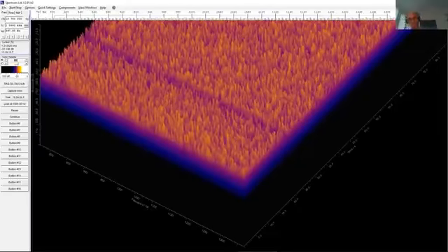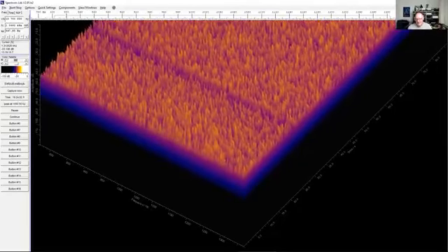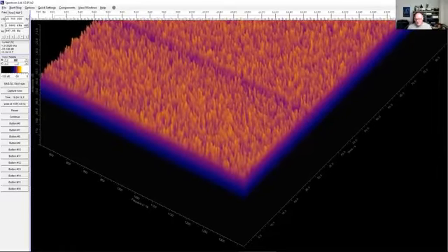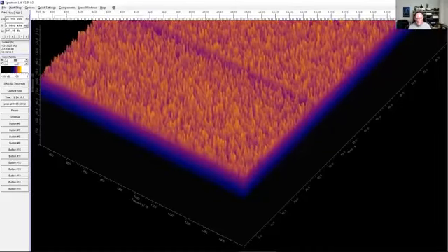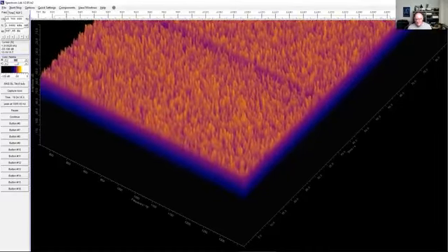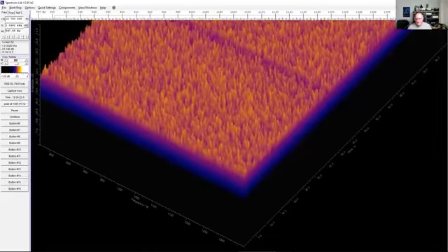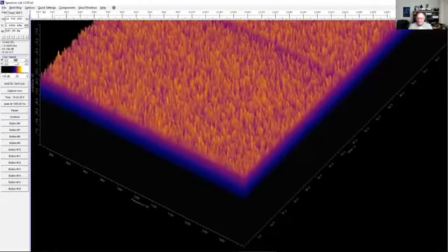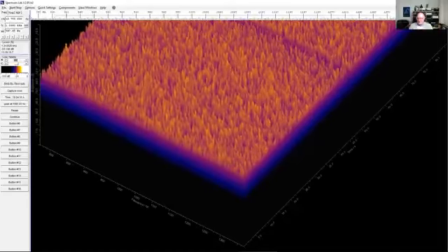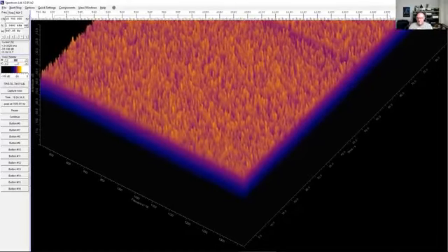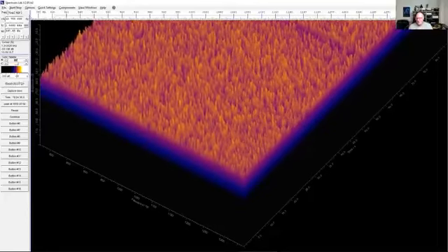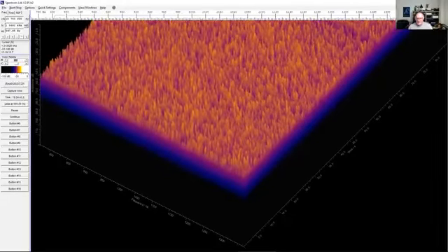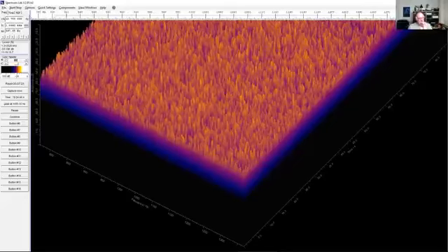So again, technically for receive you can use 75 ohm or 50 ohm, but 50 ohm is generally better. But if you get some of the better quality amateur radio stuff, that is usually better at rejecting interference, because again, the idea is the signal that you pick up with the aerial is what you want to go into the pipe, which is your coax, and you don't want that to be interfered with until it gets to the computer end and gets processed. So ideally, the better shielding you have throughout the system means that little bit of a signal that you get will be hopefully reflected in a little bit of a display.